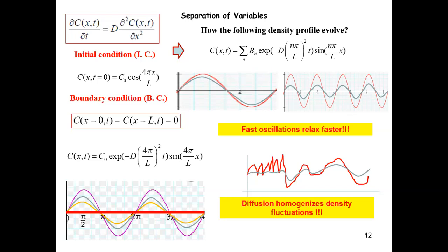And this is typically the way people use diffusion to treat materials. Initially, you have some carbon, not quite uniformly distributed in the system. What they do is take a metal bar, typically an iron bar with carbon atoms, and heat up the system to increase diffusion, because we know the diffusion coefficient, this diffusivity, depends sensitively on temperature. So they keep that bar at elevated temperature to accelerate the diffusion, and after some time you get a very nice and almost homogeneous profile for the carbon in your system, which is going to improve the mechanical property.